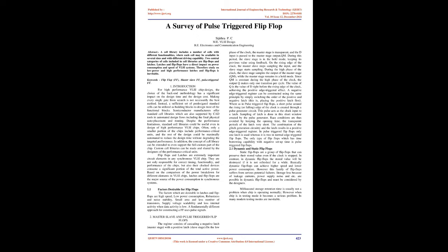Flip-flops and latches are extremely important circuit elements in any synchronous VLSI chip. They are not only responsible for correct timing, functionality, and performance of the chips, but also their clock devices consume a significant portion of the total active power. Based on the comparison of the power breakdown for different elements in VLSI chips, latches and flip-flops are the major source of the power consumption in synchronous systems.